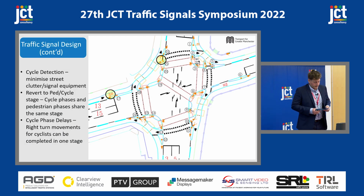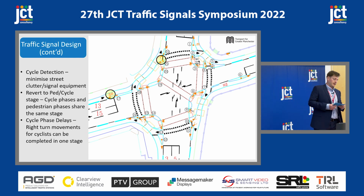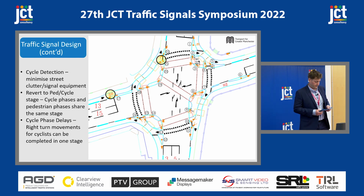So other things to consider in the traffic signal design, which are more related to time rather than the physical 2D geometrical design, are things such as cycle detection. So this could be in the form of subsurface loops, piezo strips, or overhead detection, and these can be placed to place advanced demands for cycle phases. So you can minimise street clutter by not requiring an additional push-button unit pole, and then the push-button unit can be placed on the most appropriate cycle signal pole and also be used as a fallback in the case of a loop failure.